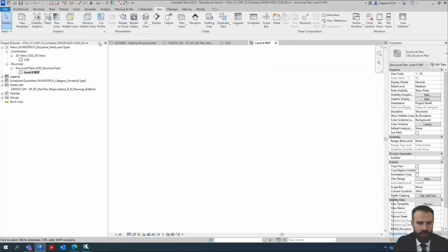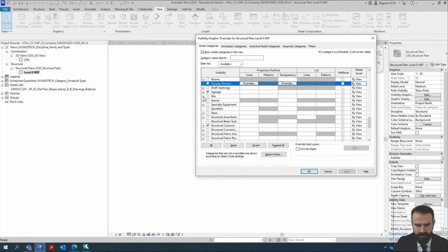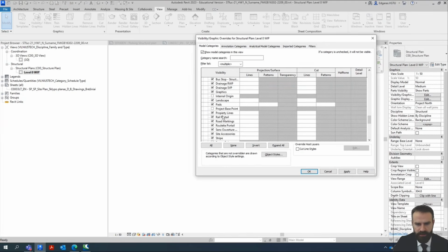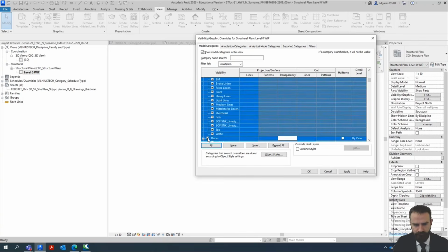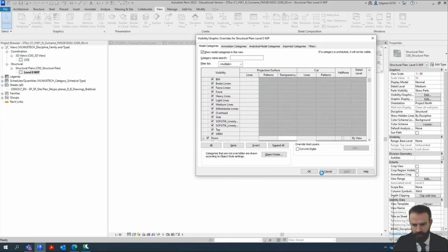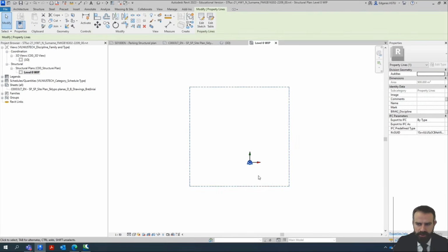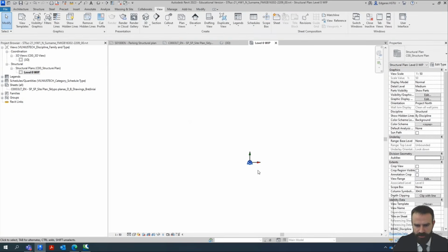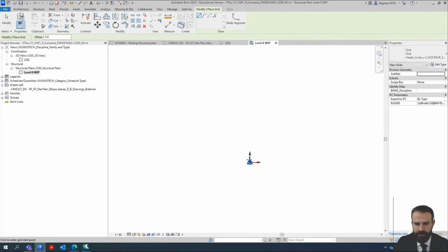Nope. And I would like to see my coordinate system. So in this case, I will select site and turn on all parameters. Basically, I can expand and turn on all things. Click apply. Okay. So the property line is also not needed. And on this location, I will go to architecture, select grids, and draw a basic grid line.